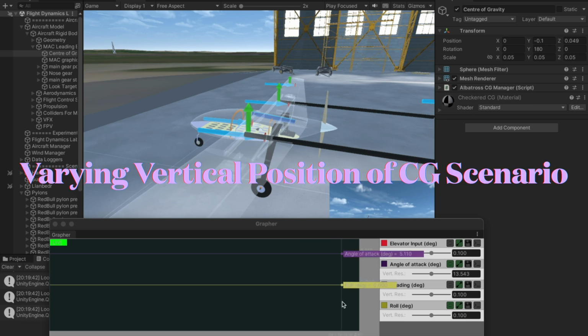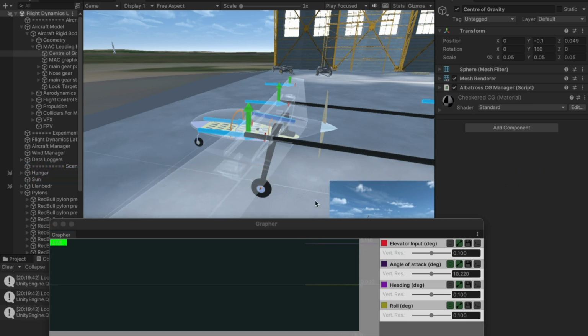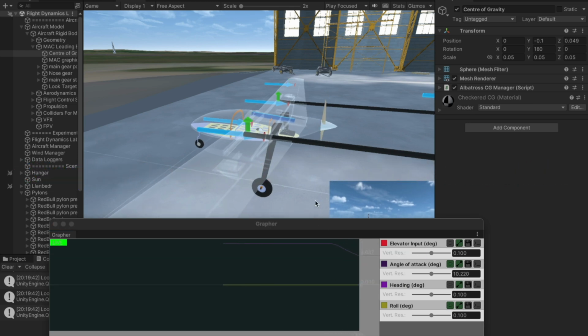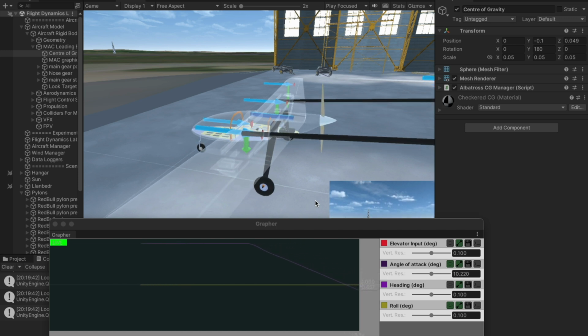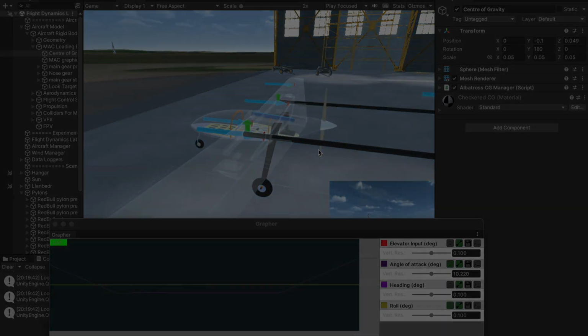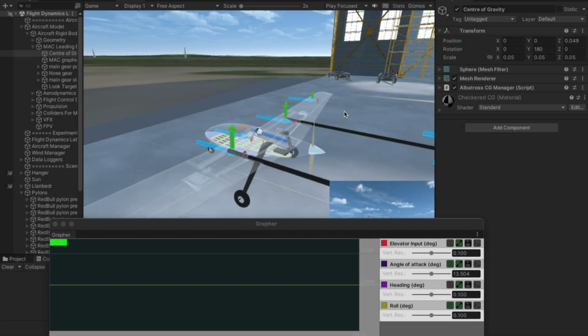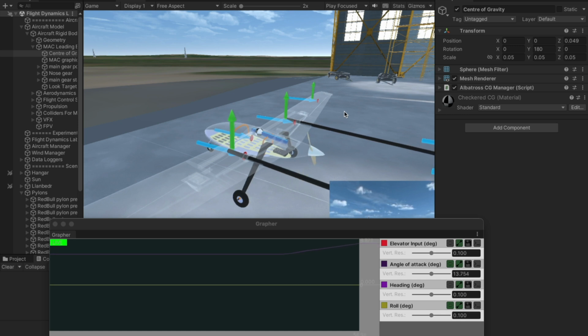After that, the aircraft longitudinal stability and reaction to shifting the center of gravity was evaluated. In this clip, the aircraft CG was put at 3 different locations. First, -0.1 meters, which resulted in nose-down moment. Next, the CG-Y component was put at 0 and resulted in nose-up moment.